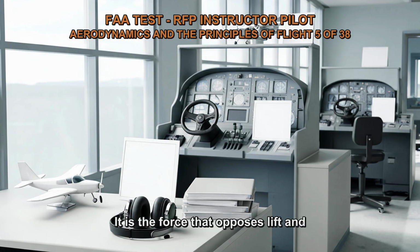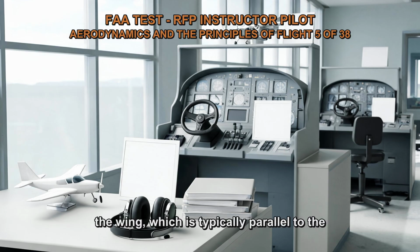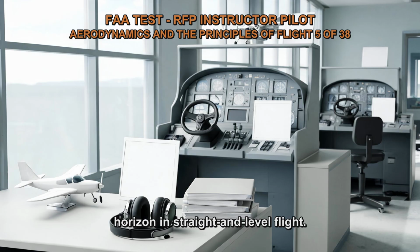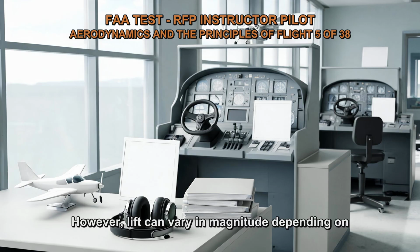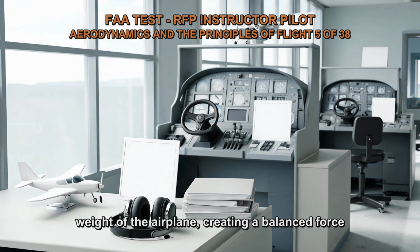It is the force that opposes lift and is determined by the mass of the airplane and the acceleration due to gravity. Lift is the upward force generated by the wings of the airplane as a result of the airflow over them. Lift acts perpendicular to the longitudinal axis of the wing, which is typically parallel to the horizon in straight and level flight. However, lift can vary in magnitude depending on the angle of attack and the airspeed of the airplane. In straight and level flight, lift is equal to the weight of the airplane, creating a balanced force situation.